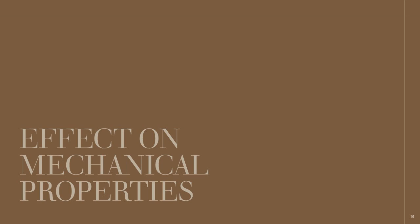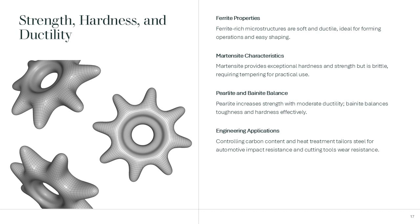Effect on mechanical properties: strength, hardness, and ductility. Microstructure directly influences mechanical properties. Ferrite-rich structures are soft and ductile, suitable for forming operations. Perlite increases strength while maintaining moderate ductility. Martensite offers exceptional hardness and strength but is brittle, requiring tempering for practical use. Bainite provides a balance of toughness and hardness.